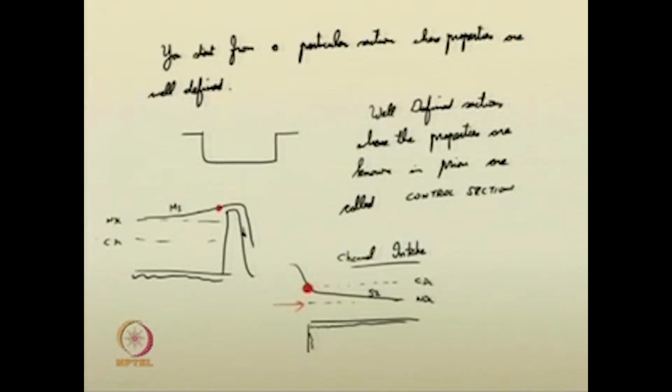So, we have to note that usually the subcritical flows have control sections at the downstream of the profile, that is, subcritical flows have control points at the downstream end, as you have seen in the spillway example in the previous slide. For the M1 profile, it starts somewhere here and goes like this, but the control section is at the downstream of this profile.